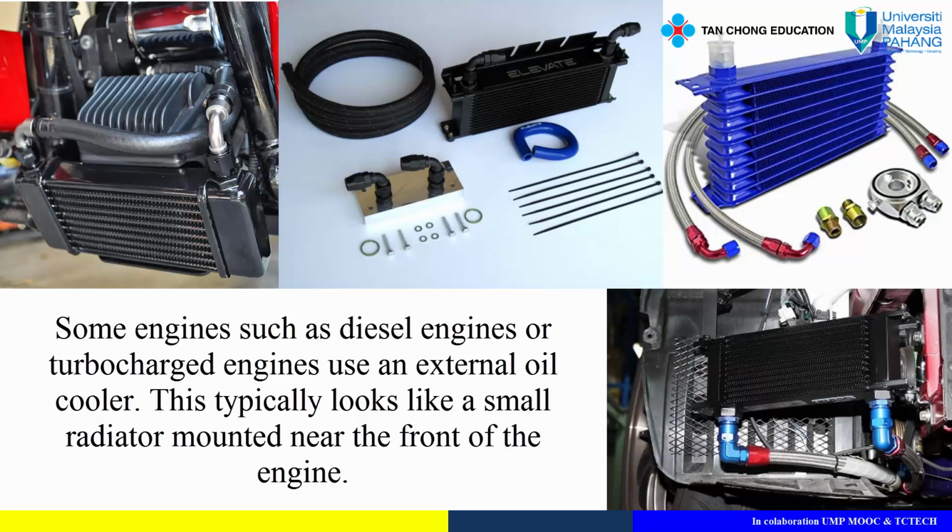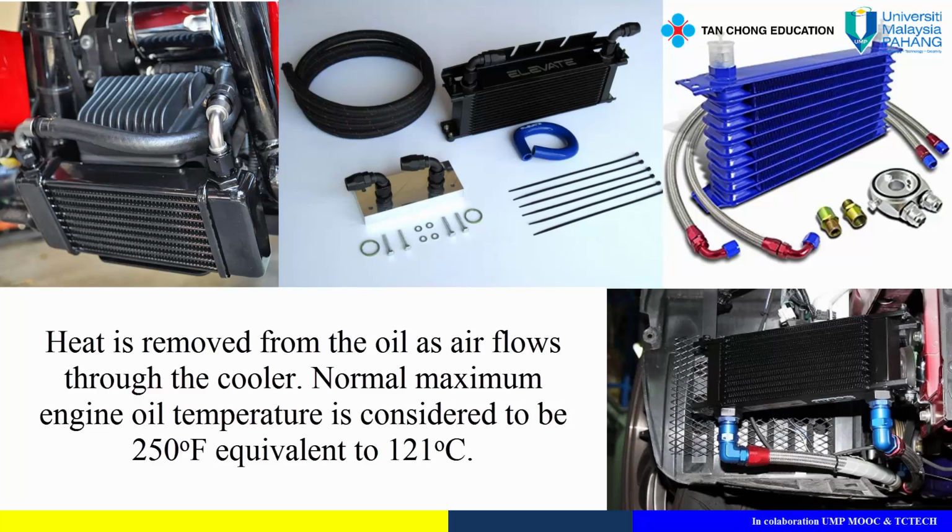Oil cooler. Some engines, such as diesel engines or turbocharged engines, use an external oil cooler. This typically looks like a small radiator mounted near the front of the engine. Heat is removed from the oil as air flows through the cooler.